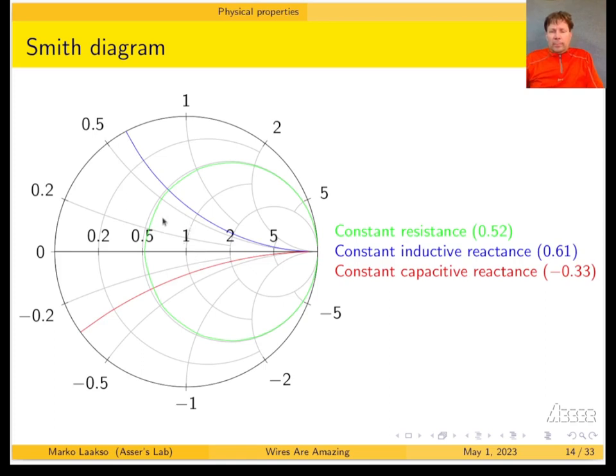And now we can plot different frequencies on here and see how the total impedance behaves and how it's constituted from the resistance and the reactance. We will see examples later on where this makes sense, because for the frequencies it actually often makes these circles, and that all comes to those wavelengths.